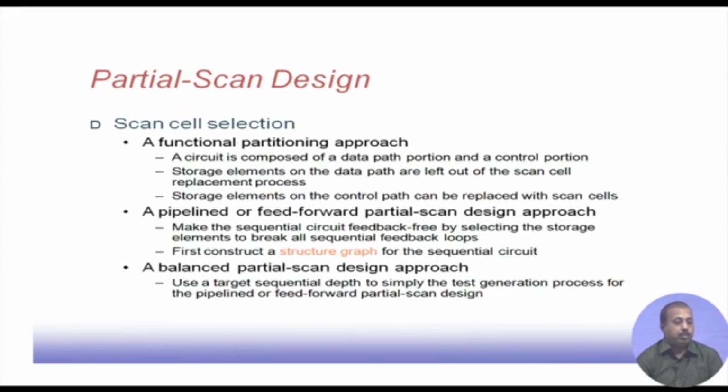composed of a data path portion and a control portion. The data path portion is doing all the computations, like there are registers, multipliers, multiplexers, adders, subtractors, and so on. So, they are forming the data path.